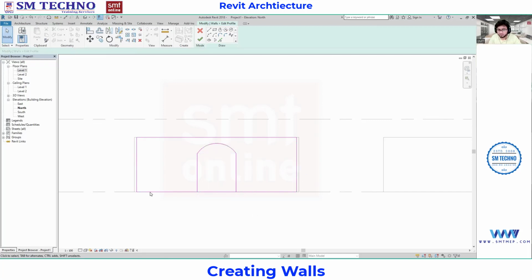Fine. Now this should be in a continuous path. This is not continuous right now because the line is going somewhere over here. Again, the line is going upside over here also. So from the modify tab, we have to go with split. We are going to break, like in AutoCAD we have got the divide. So go with the split, select the point from. Right click cancel, right click cancel.